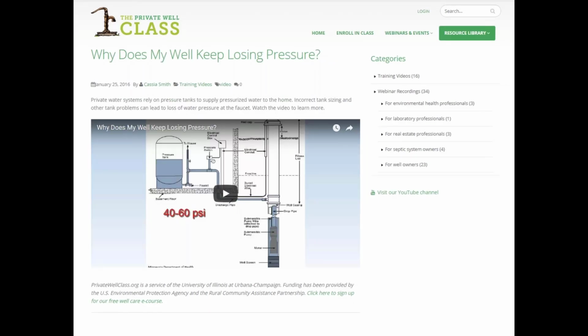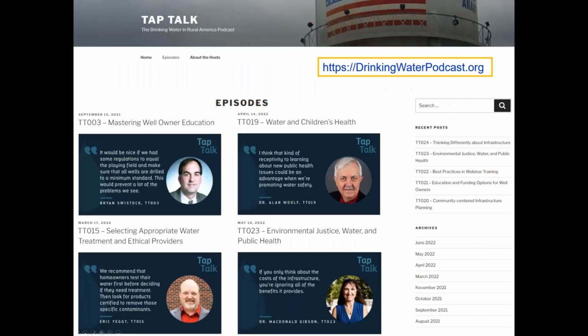Our most popular video, I think it might be, is how does my pressure tank work? Well over 400,000 views. What we've learned from that is a lot of people have pressure problems that own private wells, and that's probably because of an undersized pressure tank or not having your pressure settings in the correct place. If you have a 2-story home, for instance, a lot of times there won't be enough pressure to have very much water pressure on the second floor.